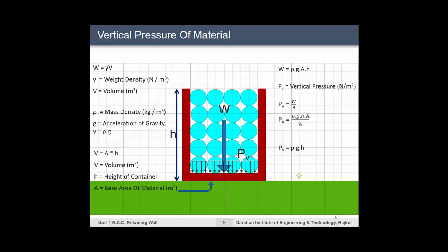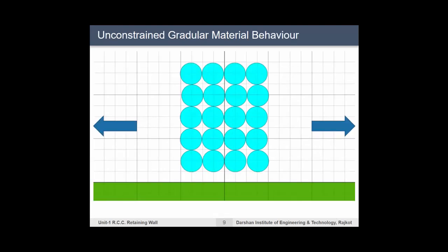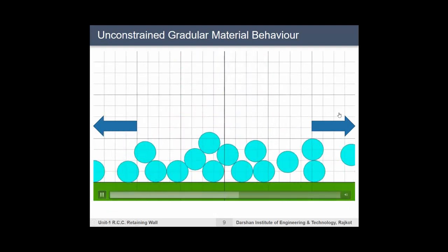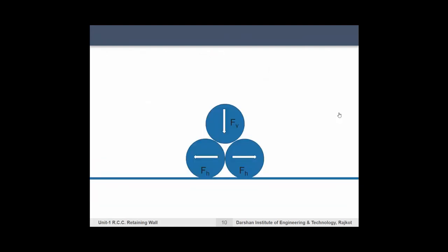Wooden cylinders also exert a push force on the sides of the container. If we stop them by the container wall, nothing else stops them from pushing outwards. To understand why this outward force arises, consider three cylinders from the original stack. As gravity pushes the top cylinder downward, it tends to squeeze between the other two cylinders, pushing them outwards.